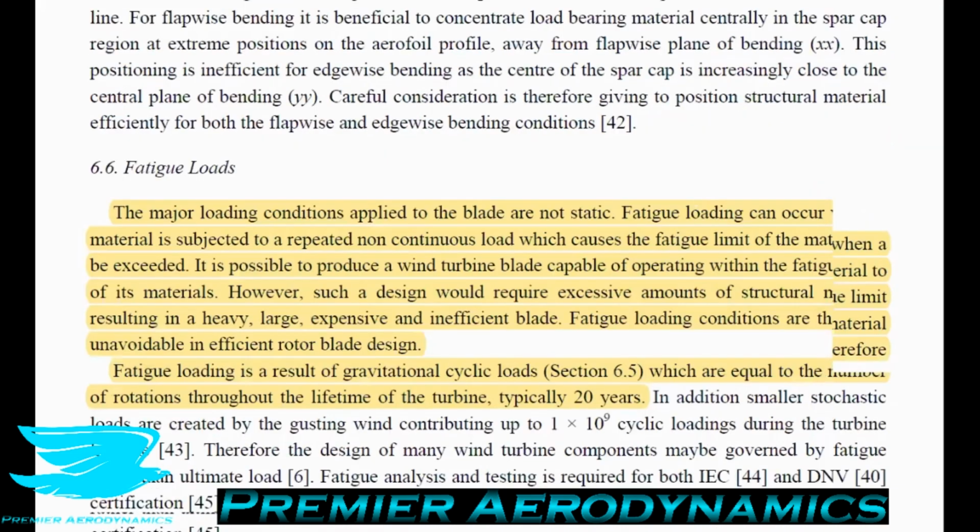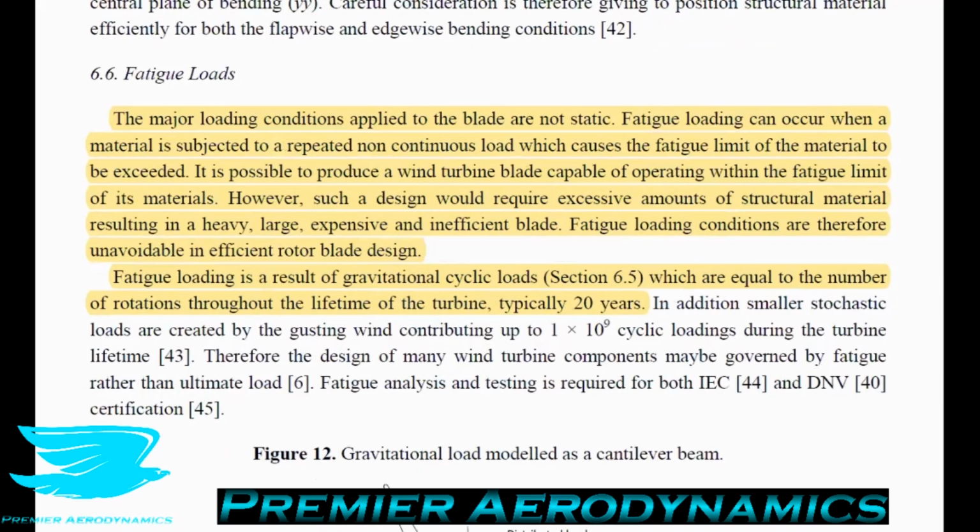Now, fatigue loadings. Fatigue is something that we don't really talk about too much in most things, but is really important because fatigue is responsible for so much more destruction than people think. Fatigue is when, let's say you have a piece of metal and you just bend it back and forth a bunch of times. By the end of it, you can break the metal with far less force, far less stress on the object than if you were to just break it straight away. That's because as you bend something more and more, that's fatigue and it weakens the object.